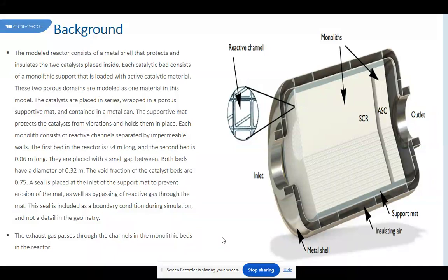It should be pointed out that there have been several efforts on improving the fluid distribution inside a catalytic converter by adding diffuser elements, changing the inlet cone, and similar solutions. But using an optimized combination of cell densities, washcoat loading, and so on has not been explored extensively yet. The temperature distribution was also analyzed. According to the results in this simulation, the temperature fields of the four cases are similar.